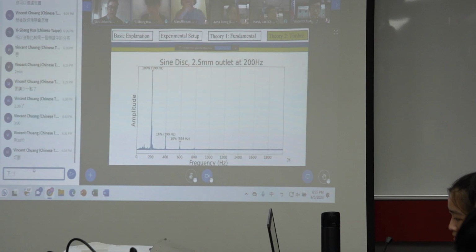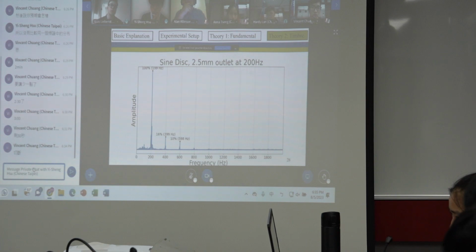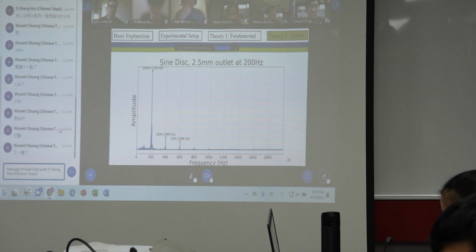So you can see that the noise is really irrelevant to the problem itself. This is motor noise probably, because motor noise is usually about 50 hertz, but this is very good experimental data. The peaks are like 20 to 30 times the size of the actual disturbances, which is basically as good as it gets.